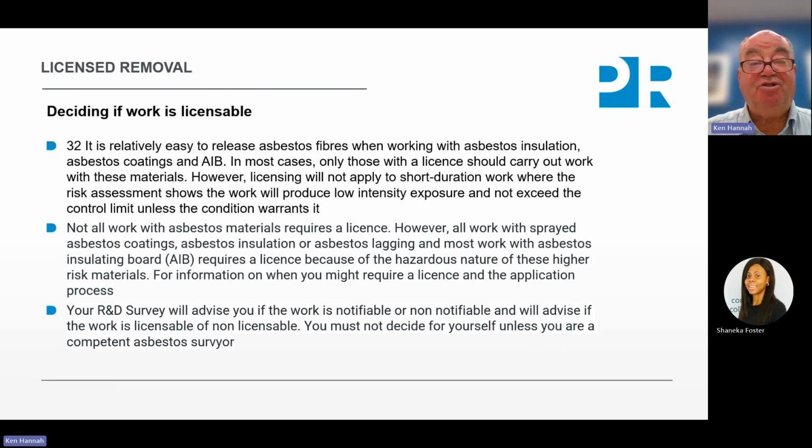So licensed, non-licensed, notifiable, non-notifiable, it's a bit of a circle. So it is easier to say that the R&D asbestos survey will advise if it's notifiable or not notifiable and who to notify it to, but it's usually the HSE in the construction industry, and also if it's licensed or non-licensed. So you don't have to decide, because after all, you don't know what kind of asbestos you're looking at, and you don't know what the condition is and the seriousness of it.